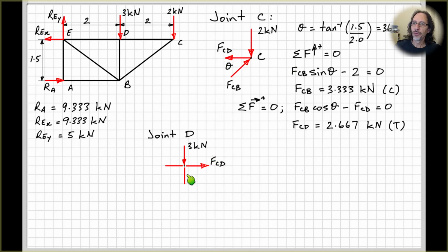All right, so then we've got 2 unknowns left. We've got forces in ED and BD. So it's pretty easy in this case to work out where to put the arrowhead. The only force we've got acting vertically other than our load here is our force DB, so that one has to be up. And then on the left hand side here, our force in member ED must be acting to the left for this to be in equilibrium. Label those with some labels that we can use in our equations.